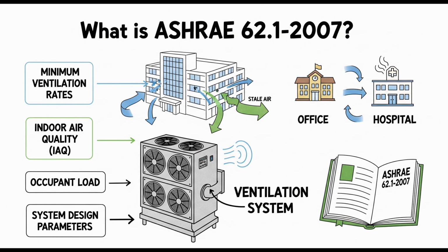The standard says, before you finalize the ventilation design, you must investigate the quality of the outdoor air right there at the site, and you have to document it. Investigate how? Two main ways. First, check if the region complies with national air quality standards.